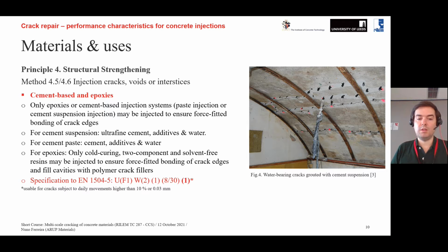So that's why you put the one here, which is 10%. But again, very important to note, epoxy should only be used in dormant cracks. They don't change the crack width often, but can accommodate slightly small movements because of vibration and so forth. This is probably of interest for wind energy towers or wind energy foundations, if you really want to reinstate capacity across the crack.